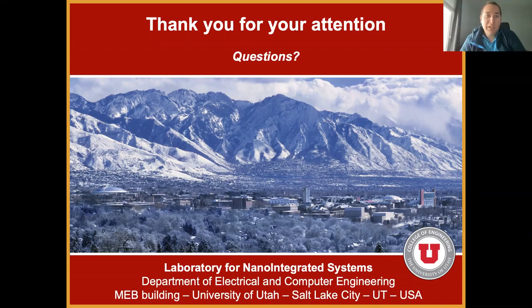And in the end, when you look at logic synthesis in FPGAs, it is so tightly linked to physical design that it makes things hard to decorrelate, right? You get a much better performance at your synthesis level, but you just exploded your fan out and timing inside of the fabric. So you need to make your fabric evolve. But then, is the synthesis better or is the fabric better? Hard to get a fair answer to all of that.